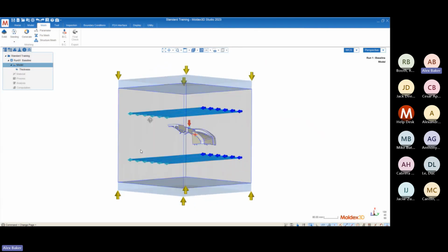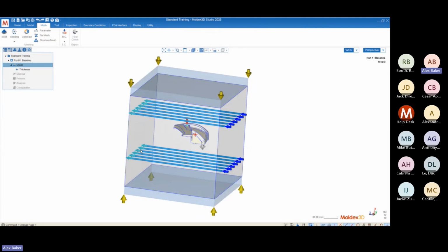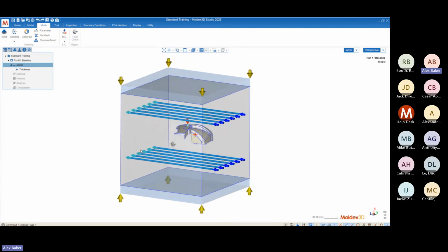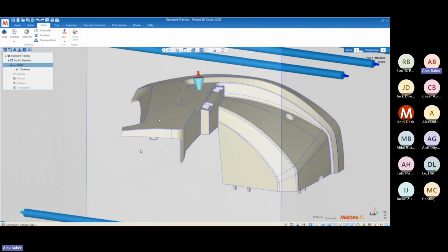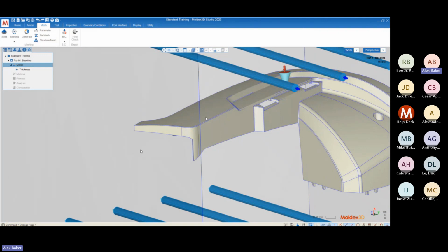When we're talking about meshing in the solid mesh specifically, in the solid meshing style, I should say, there's two meshes that are going to be created for every geometry object. There's going to be a surface mesh and there's going to be a solid mesh. A surface mesh is going to be breaking down all of the individual surfaces in our geometry into a series of triangular surface mesh elements. And then we're going to fill in those surface mesh elements through the thickness of our part with a solid mesh. All right, so there's two meshes that we need to specify the parameterization for.